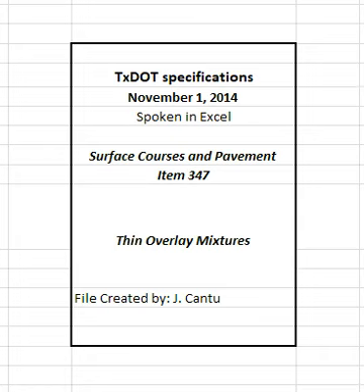The engineer may allow alternate methods for determining the asphalt binder content and aggregate gradation if the aggregate mineralogy is such that Tex-236-F does not yield reliable results. Provide evidence that results from Tex-236-F are not reliable before requesting permission to use an alternate method unless otherwise directed. Use the applicable test procedure as directed if an alternate test method is allowed.